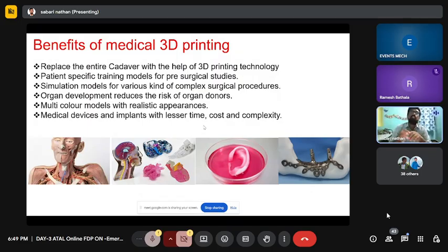So you can mix multiple materials. If you select a polyurethane material with the lowest Shore hardness and combine it with PLA, you can make some kind of pre-surgical models using the FDM process itself. You can't match exactly the human organs, but you can match somewhat.